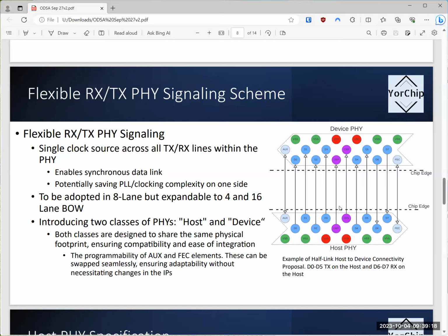Well, that's the thing, right? You're removing the flexibility of TX and RX having mixed flexibility and asymmetricity. What happens if you want to do 2 transmit and 4 receive? I would say if you take the step of the by 4 and, as Elad was saying, make it all one directional in the first step, then you can still define this add-on mode, where with these 4 you can decide how many are RX and how many are TX, but that mode will only be supported if it sees exactly the same PHY on the other end. Yeah.